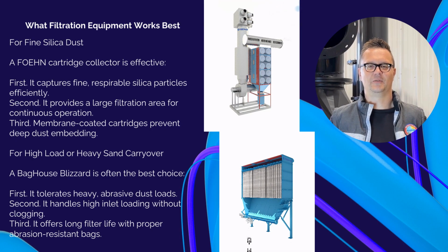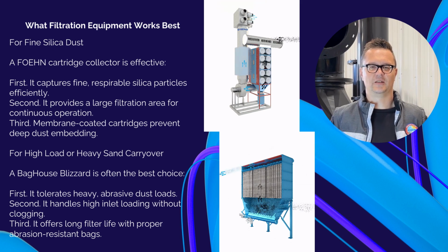For high load or heavy sand carryover, a baghouse is often the best choice. First, it tolerates heavy abrasive dust loads. Second, it handles high inlet loading without clogging. Third, it offers long filter life with proper abrasion-resistant bags.